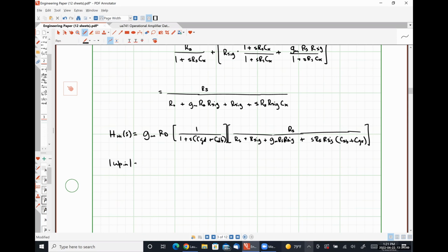So we're gonna have a pole associated with that voltage divider at the input. So I'm calling that pole omega Pn. So the pole of this guy is the value of S that will make this whole thing 0, right? Typically speaking, we have it in the form of 1 plus S blah, blah, blah. So effectively, this bit right here is going to be our denominator. And then this bit right here is going to wind up in the numerator so that it cancels correctly. 1 plus S RD.